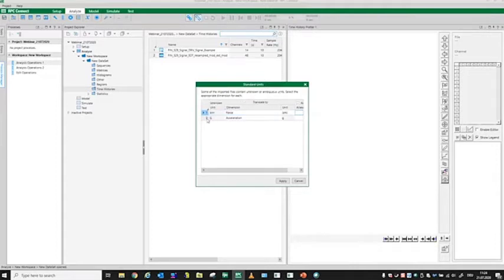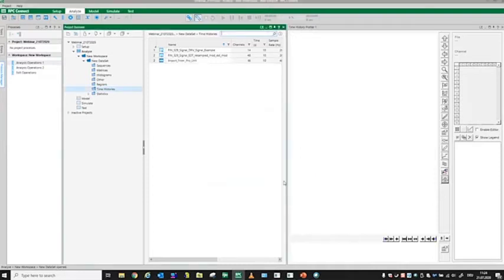So for example, G is always not in a capital letter, so it's of course an acceleration, and I need to make sure that RPC knows that the little g is the big G in my RPC Pro file. So once you hit apply, now RPC is taking care of your units.